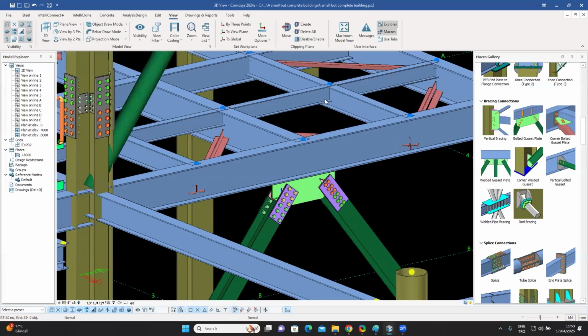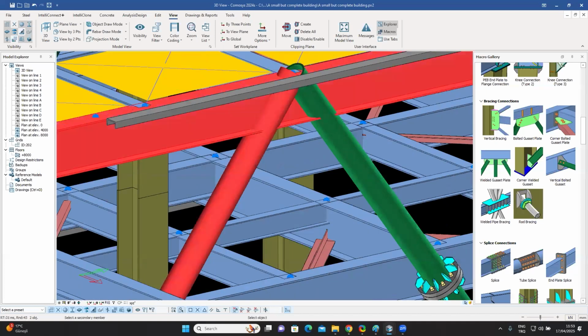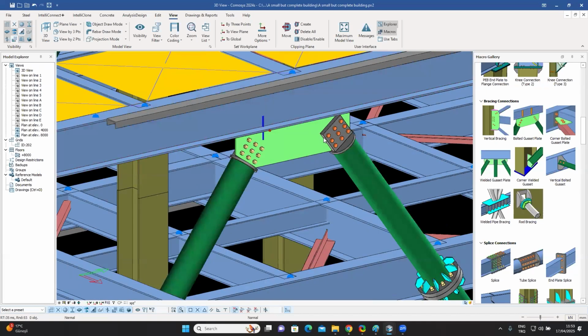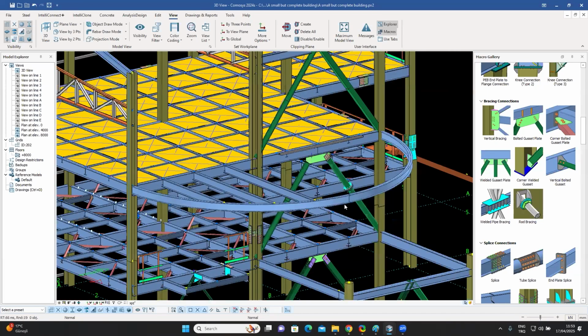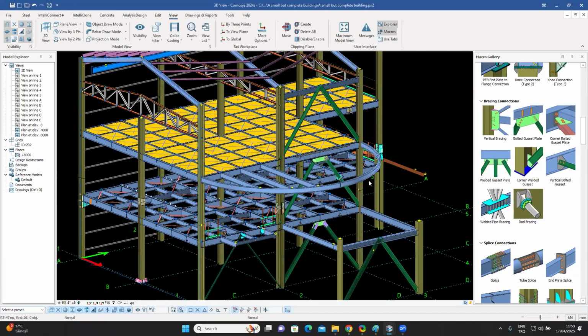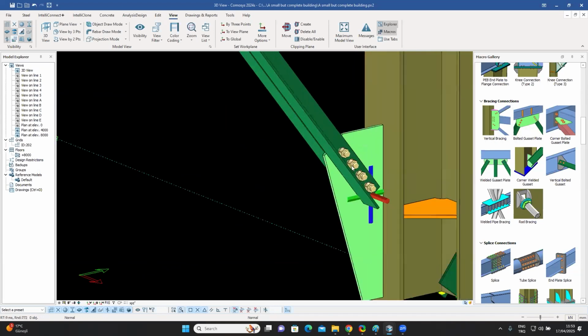Like I said over here, you can use the same command, this one and this one, this one, and right click, and you can have a pipe. Basically, what you're noting over here is that the same macro is being used again and again for different types of vertical braces. Let's go in and try to use it for example, a twin profile, a back-to-back angle in this case. Once again, the same command, I can use my column and my secondary one, and my connection is